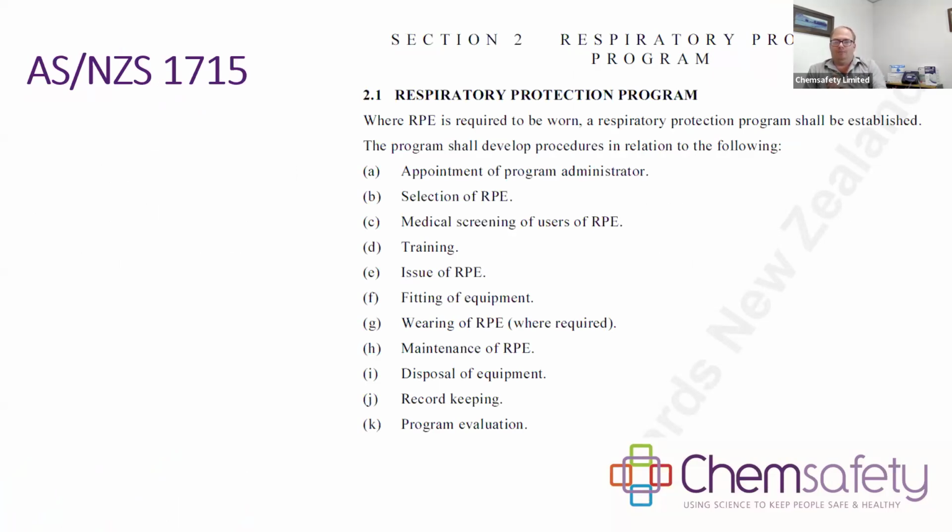When you use RPE per the standard, a respiratory protection program shall be established. It needs to have a person who's going to run that program. It's going to have a process for selecting your RPE, and medical screening. All these negative pressure respirators, whether it's a half-face respirator, like these ones here, or even the disposable ones, put a lot of burden on the respiratory system because you're having to breathe through those filters. It gets a lot harder to do that. So people with asthma, COPD, or other cardiovascular issues might find that they're not suitable to be wearing these for prolonged periods of time, hence the medical screening.